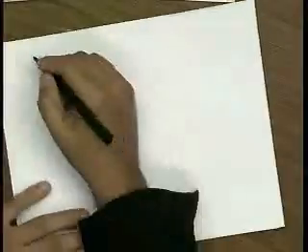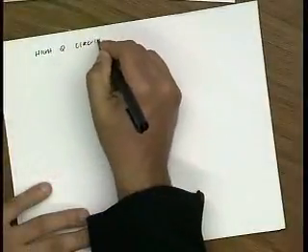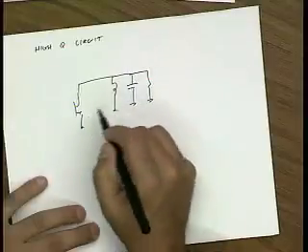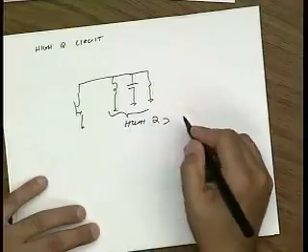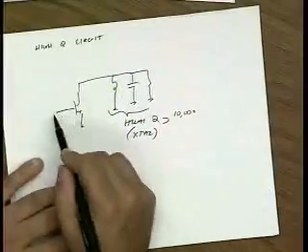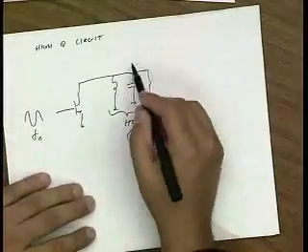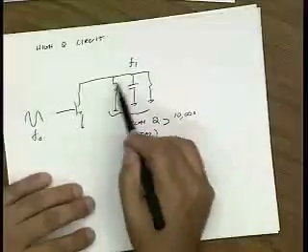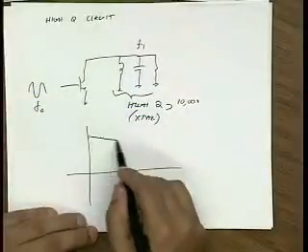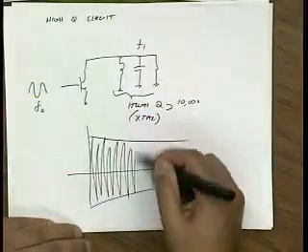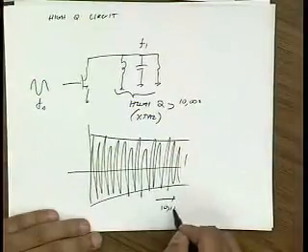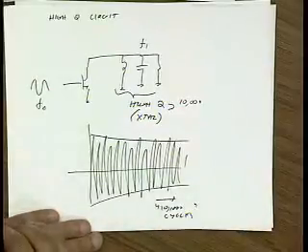So let's look at a high Q circuit. So let's say I have an amplifier and the output has a high Q tank. And let's say it's really large. Let's say it's 10,000. Okay? For instance, this might be a crystal at the output. If I put in a sinusoid F0 close to this frequency, then I'm going to basically have to wait until the natural response of this crystal dies off. So if I basically just turn this circuit on, it'll start ringing like a bell. And this ringing can go on and on and on, and it goes on for 10,000 cycles, right? So if I'm doing a transient, I'd have to wait 10,000 cycles, roughly, until the transient dies off.